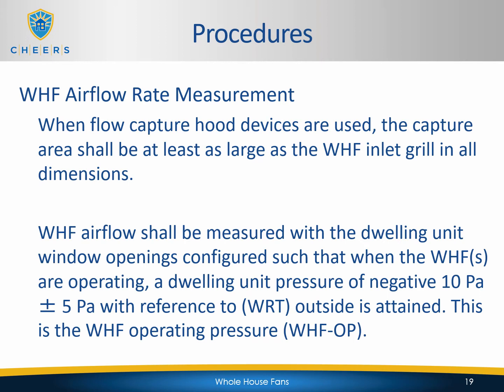So whole house fans work on the principle of depressurizing the house so that air is drawn in through windows and into the home, and then it's pushed out into the attic. So the fans are designed to run with windows open. So to test, you need to set the windows so that we get that -10 pascals inside the house. And this is going to go whether you're using the blower door or one of the flow hoods.